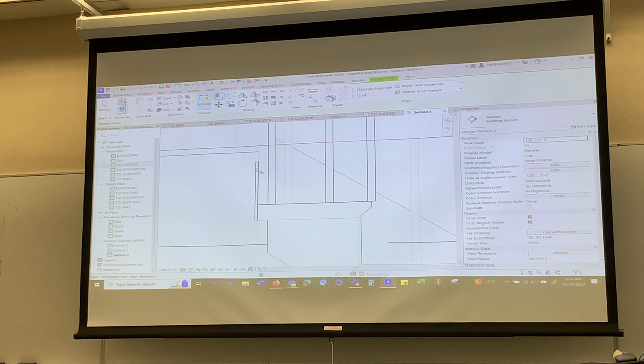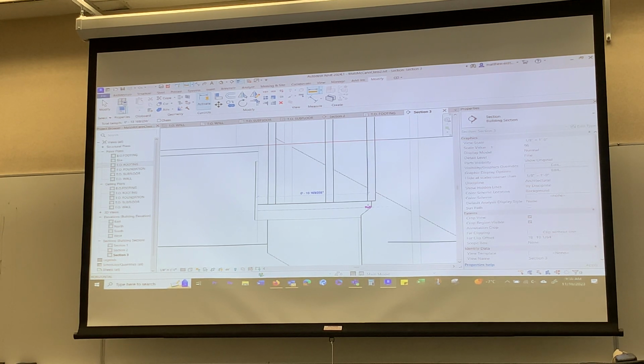Destry's correct. Normally this is a piece of 3/4 ply or something. It usually sits on the face of this thing. But to make this work properly, I want 11 inches here. You can't mess around with stairs. You can't have unequal treads and rises, or you're going to get busted, because people will fall, right?